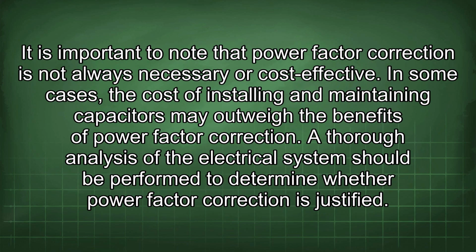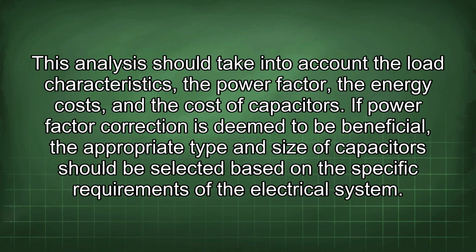It is important to note that power factor correction is not always necessary or cost-effective. In some cases, the cost of installing and maintaining capacitors may outweigh the benefits of power factor correction. A thorough analysis of the electrical system should be performed to determine whether power factor correction is justified. This analysis should take into account the load characteristics, the power factor, the energy costs, and the cost of capacitors.